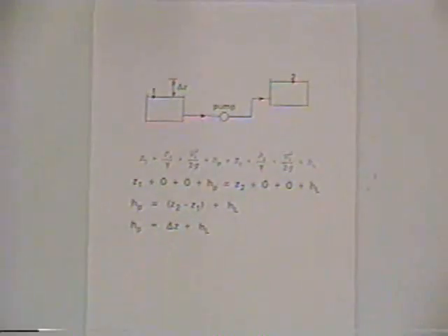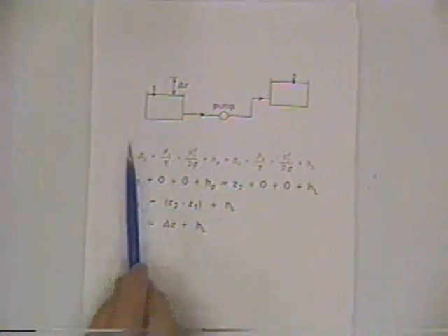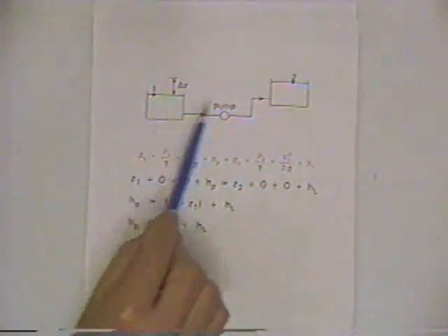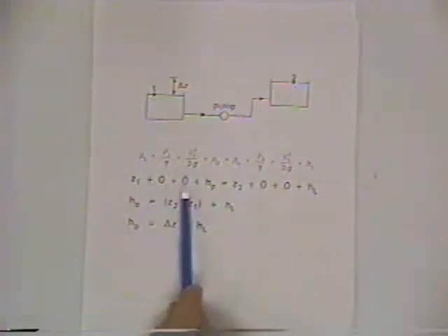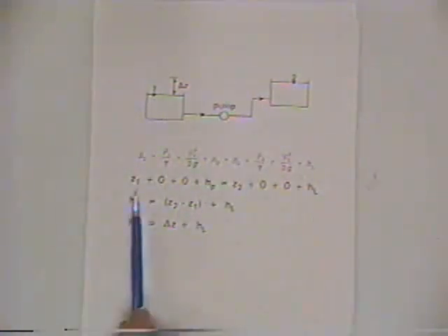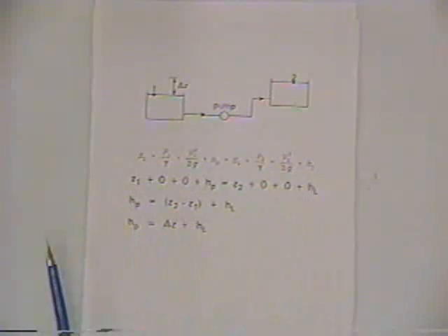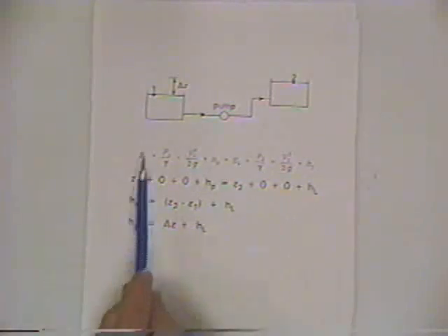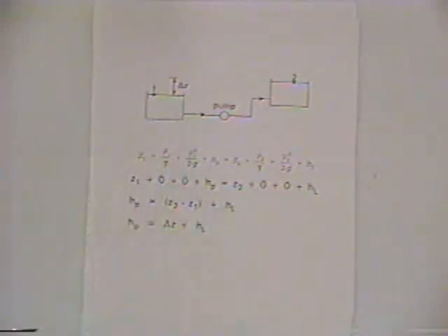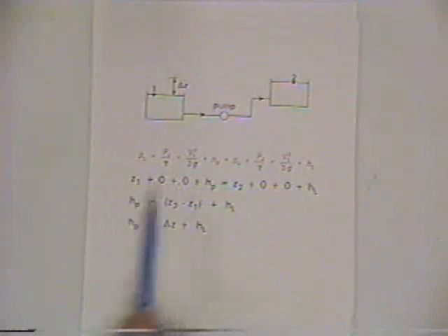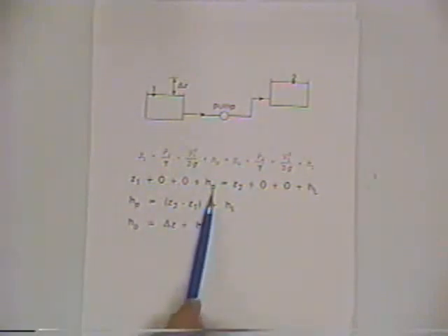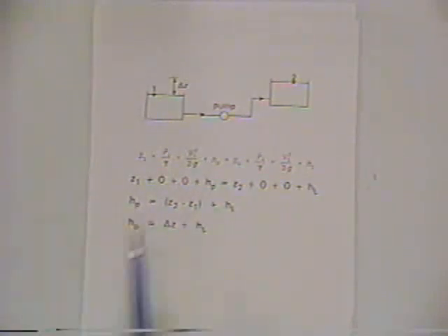We've said that if you're pumping water from one location to another, we can write the energy equation between point 1 and point 2. We write the energy equation. We substitute in the terms as we've done already. The Z we draw through the water surface and the downstream side of the pump. The pressure head 0, we're back to using gauge pressure again. The velocity head 0. The head provided by the pump.